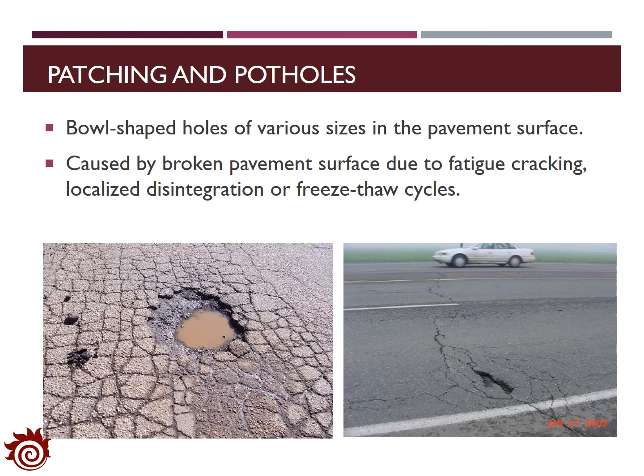Patching and potholes are also very common on the road. They represent bowl-shaped holes of various sizes in the pavement surface. Usually it's caused by broken pavement surface due to fatigue cracking, localized disintegration, or freeze-thaw cycles.